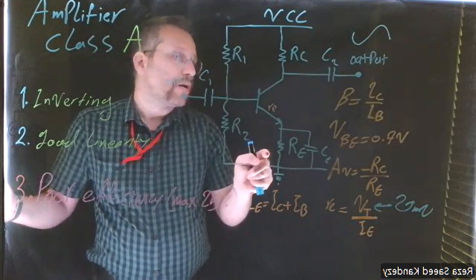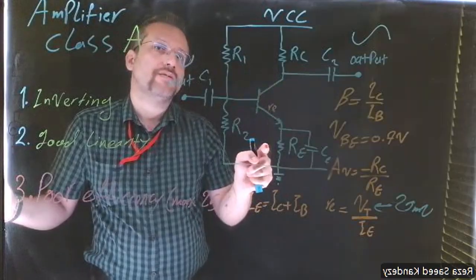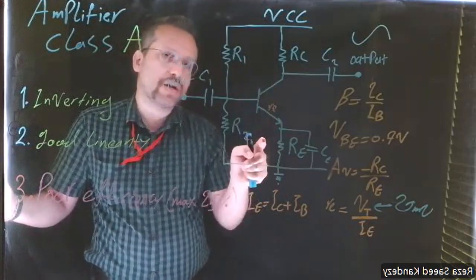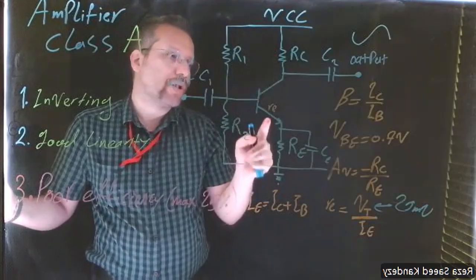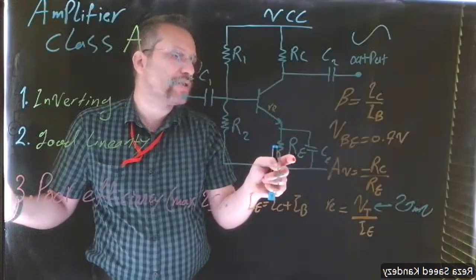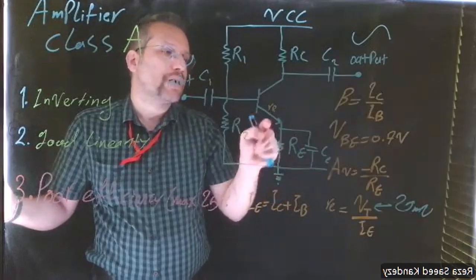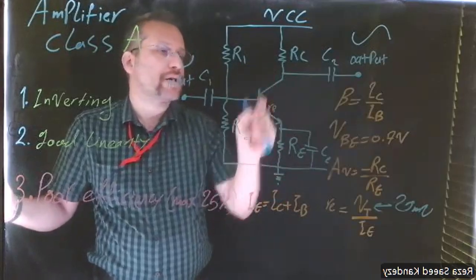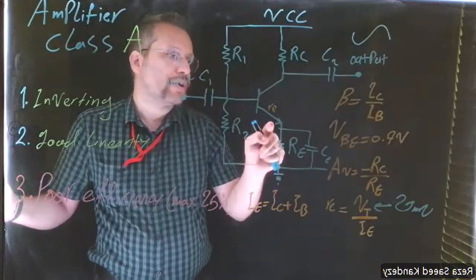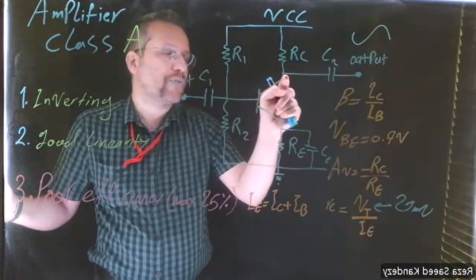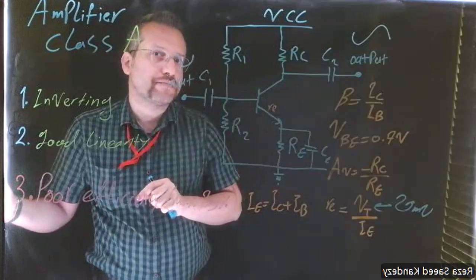Now, when we set our BJT, we bias the whole thing based on the DC component. So any AC component in the RE here would affect the biasing: the voltage across the emitter, the voltage of the emitter, the collector-emitter voltage, and the voltage of the base.